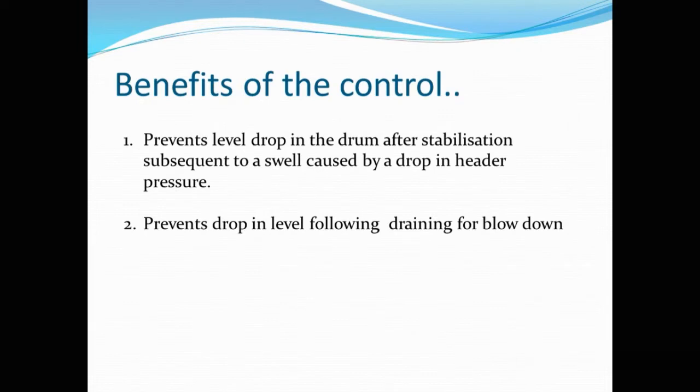The other is that at some particular frequency you are doing a blowdown of the drum to remove the salts accumulated. In that situation also the three element control system will be very effective.